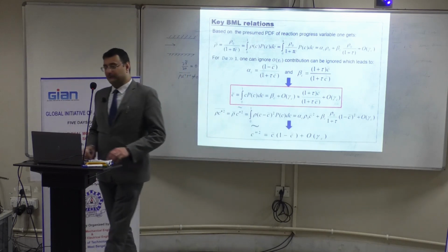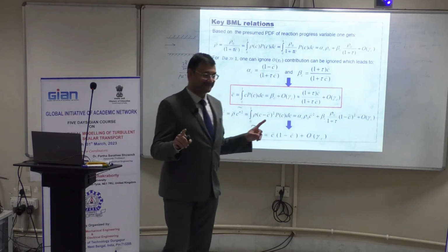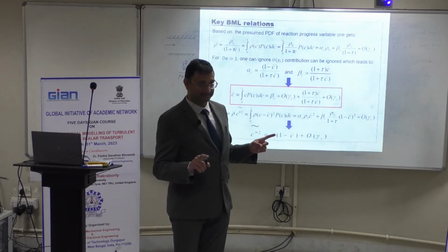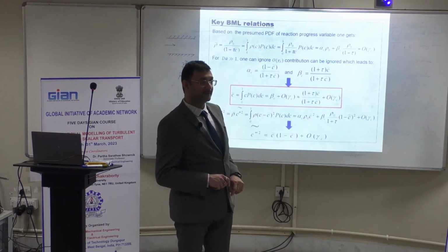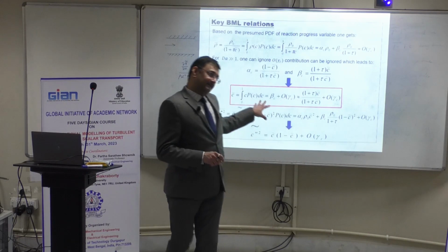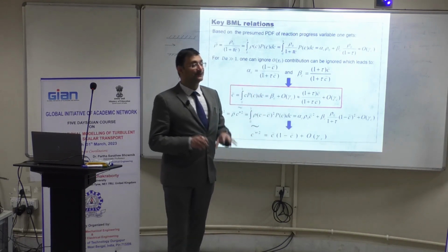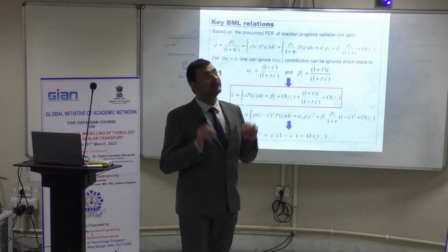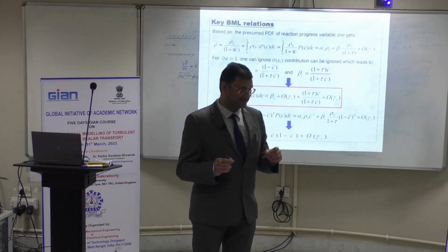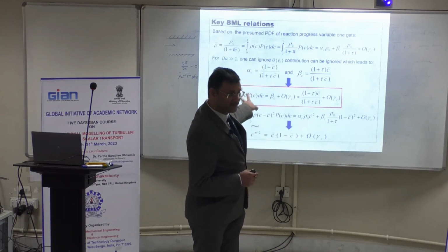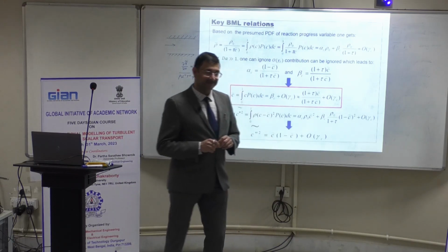Towards the beginning of the course, I already told that the Reynolds average value and the Favre average value are not the same. You can clearly see that. Okay? However, this expression is only valid for premixed flame. It's not a general expression, but at least one can illustrate that for at least one flow configuration they are not the same. They can be considerably different, actually.